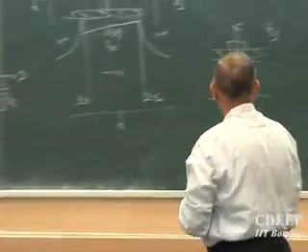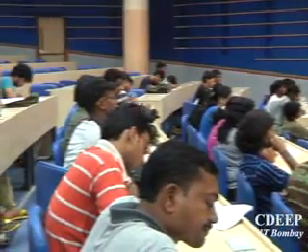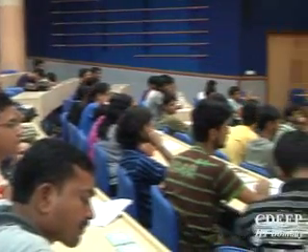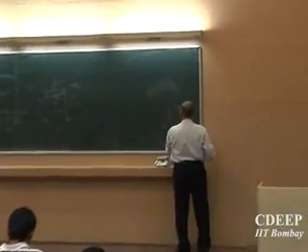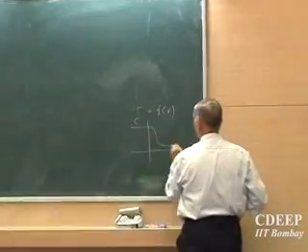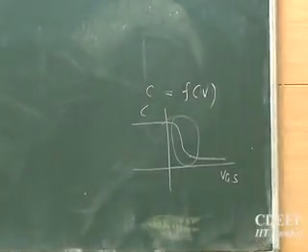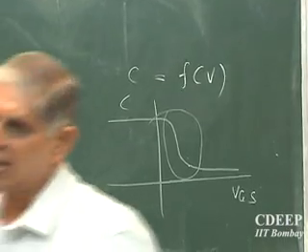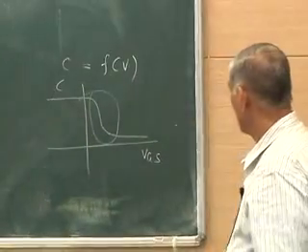Let's look at this, since this is the figure I had drawn. Maybe I should write it down correctly because I should not forget. What is a varactor? A capacitor which is a function of voltage. If I plot C versus VGS for this, as VGS changes, the capacitance changes. And this is the depletion layer. The depletion layer is proportional to the root of voltage. So it is like a PN junction with a step junction. It is similar if not exactly the same.